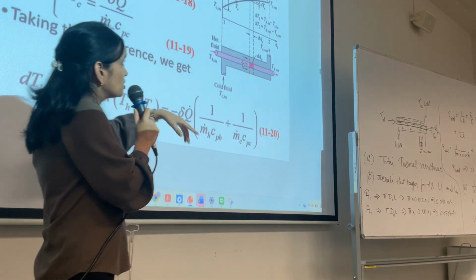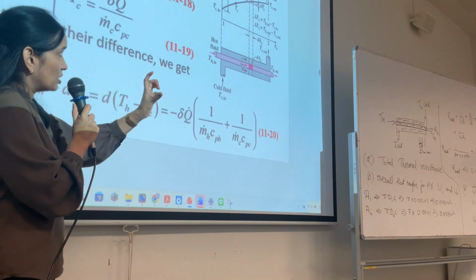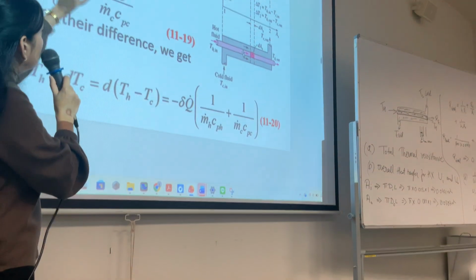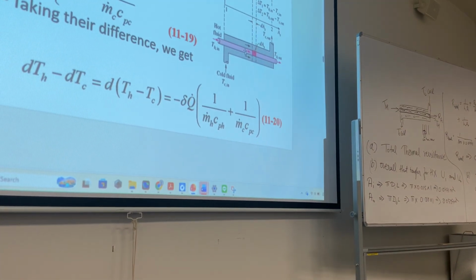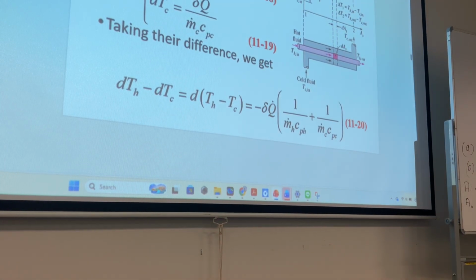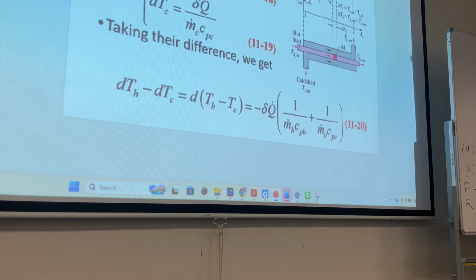This we have understood. So if you take a smaller portion, okay, and then you calculate the heat transfer rate, del Q is in the smaller region, right? Del Q, and we are using del Q because it is changing, and we are using dT because this delta T is larger here, then it decreases here, right? Del T is the temperature difference between the hot liquid and the cold liquid, and it does not stay same throughout the heat exchanger. It is very high at the beginning, then lower and lowest, right? So this del T is changing throughout the heat exchanger.